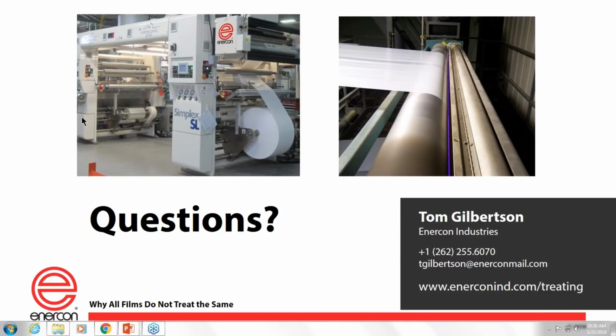In the summertime, when you have high humidity, high heat conditions, corona treaters tend to have more maintenance and service trouble because all of that moisture collects dirt, debris, additives, all the stuff that we're chasing off the film collects on the treater and requires you to clean it more often. It doesn't necessarily have a negative performance impact on the ability for the treater to treat the film.